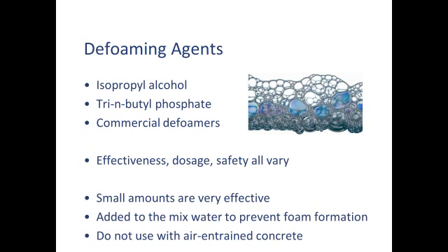Often, the way they're used is you could have your bucket of mixed water, and you just add a little bit, a few milliliters, to the mix, and it tends to look like oil, so it sort of floats on the surface. And then when you add it to your mix, it helps prevent the foam from forming. Or if you add them at the tail end of mixing, you can actually watch the bubbles burst, the foam at the surface burst. Either way is fine, but generally, if I put them up front, there's less air that stays in the concrete.